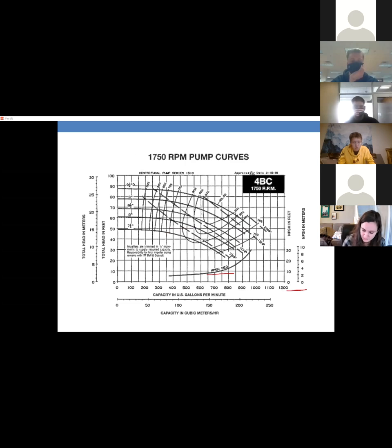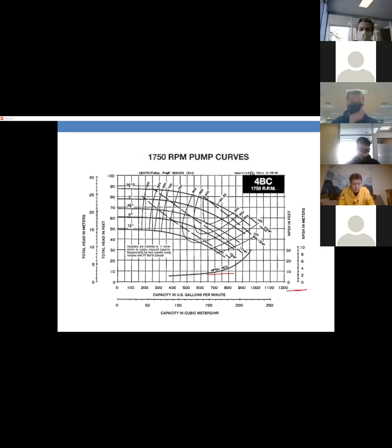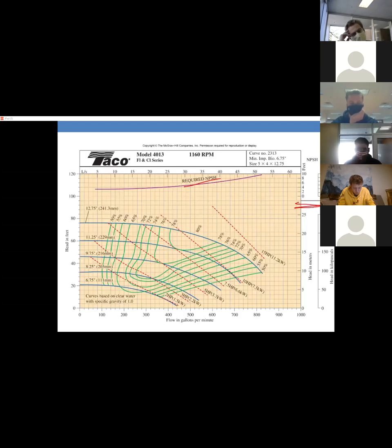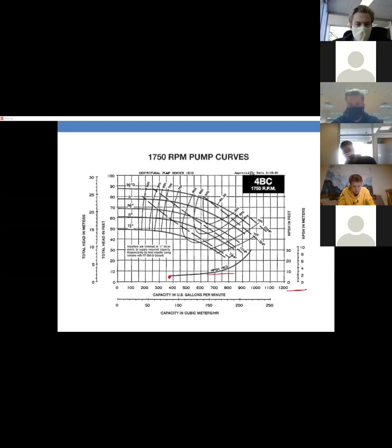All right. And looking at this one, the minimum required head is like 5 feet going into the pipe, according to this guy. 5 feet-ish, 1 meter-ish, in this example. So you can see that the minimum at low flow rates is not necessarily huge. This one needs like 2 feet at this low flow rate. But yeah, you need a bit of buffer going in.